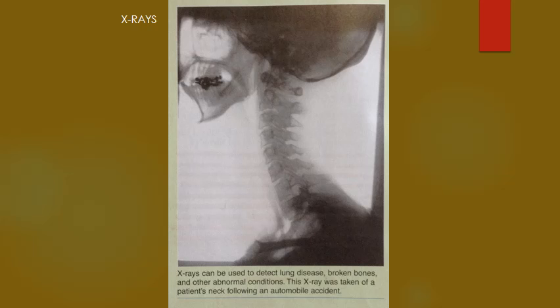When the electrons strike the surface of the anode, a great deal of heat is generated and the surface can become pitted. X-ray machines using a rotating anode are more powerful and have a longer life. The anode rotates at speeds of up to 10,000 RPM, allowing more surface area to be struck by the thermionic cloud, which in turn produces less heat.